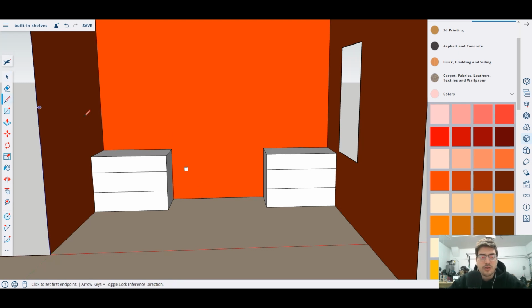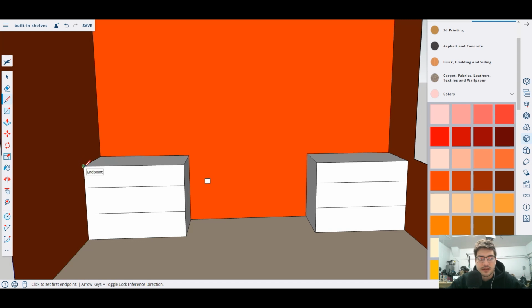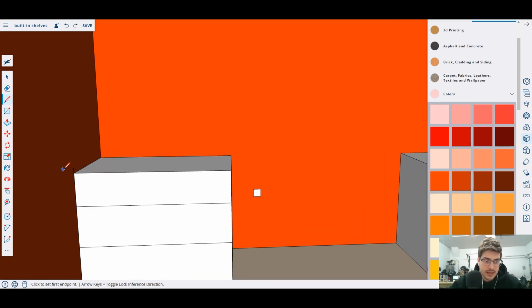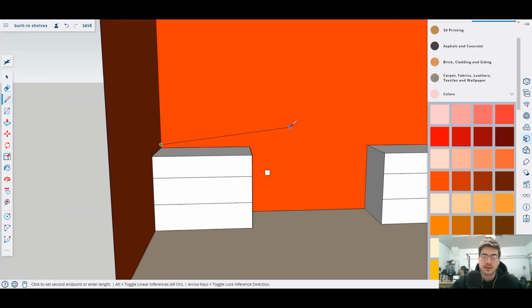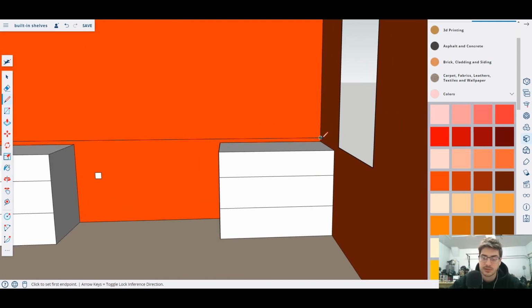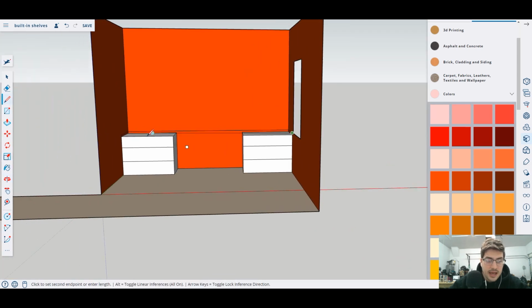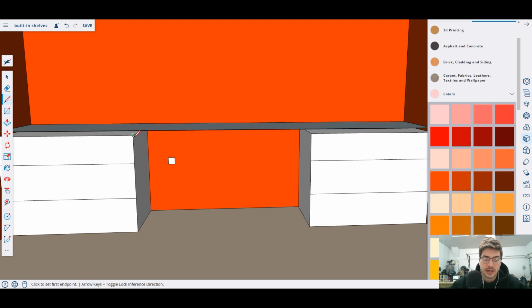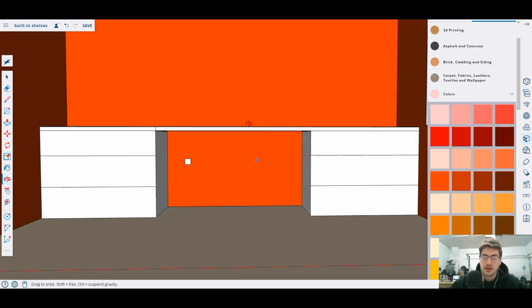Okay? Now, let's say that I want to do a sanded finished plywood, 2 layers thick. So like 3/4 inch plywood, 2 layers thick. That would be 1.5 inches high. And that is going to run the entire span, okay? Because this is kind of my desk layer. So when you go back to a built-in desk, built-in shelves kind of system, that is really your desk surface, which is going to run from end to end in the entire surface. Here is that. Okay.